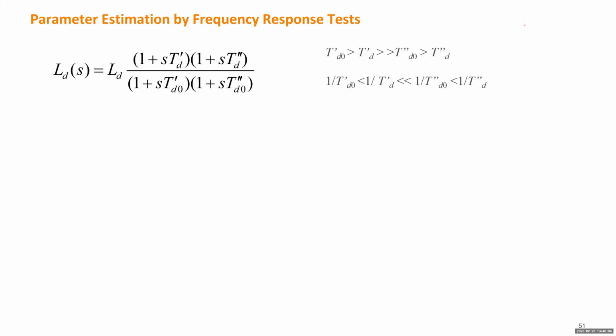Does everyone know how to draw the Bode diagram? Bode diagram is a diagram accurately characterizing what this transfer function is. There's one diagram about the magnitude, one diagram about the phase. This transfer function takes complex values. It has a magnitude, an absolute value, and also a phase. By plugging in different s, which is a complex number, you can get different magnitude and phase.